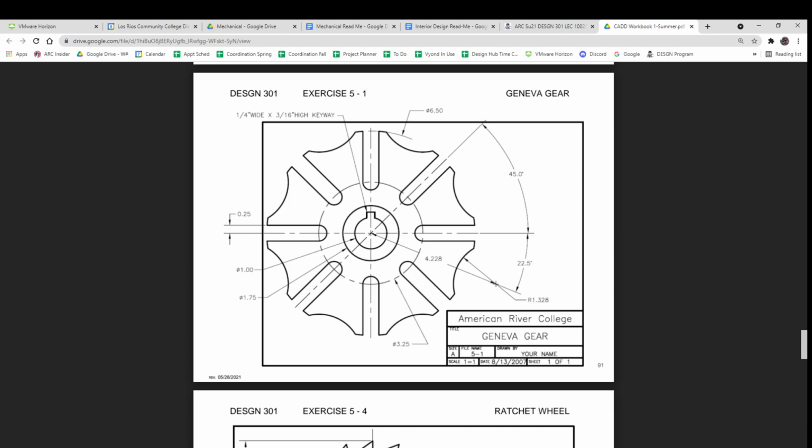Underwriters Laboratory for certain valves requires that the key in the hand wheel shears, and FM will require that the key in the gear shears.